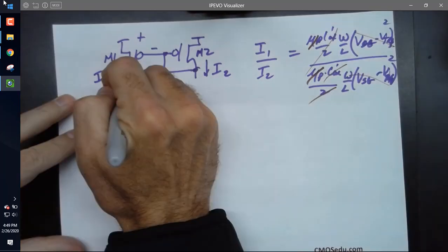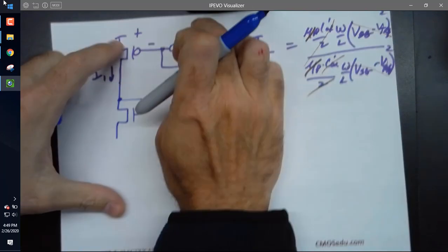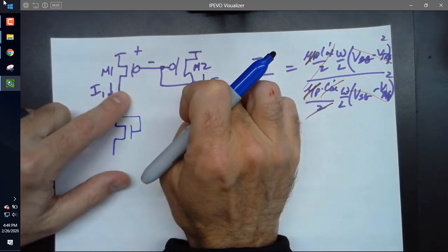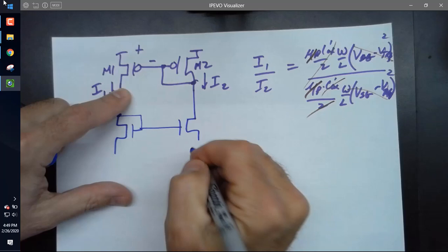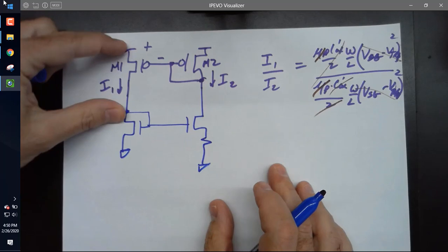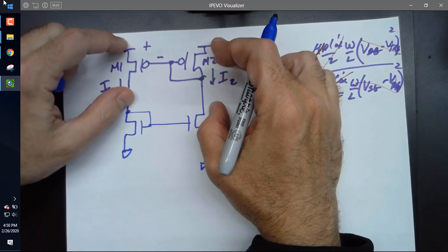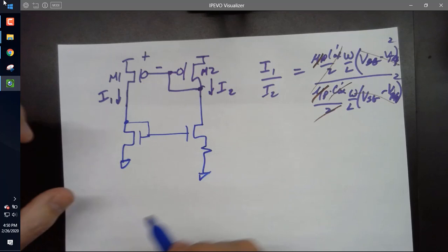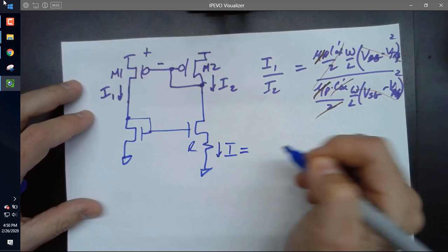Now, if it comes down here, you're going to remember the reason I gate-drain this and gate-drain this is so as VDD changes, these two voltages can move in opposite directions, because I want there to be a voltage change across this NMOS. And this one, I want to be able to have the voltage change, so I can change the voltage but the currents stay essentially the same. So now, if you recall, I want to look at, do you remember what the current was in this circuit, from memory?